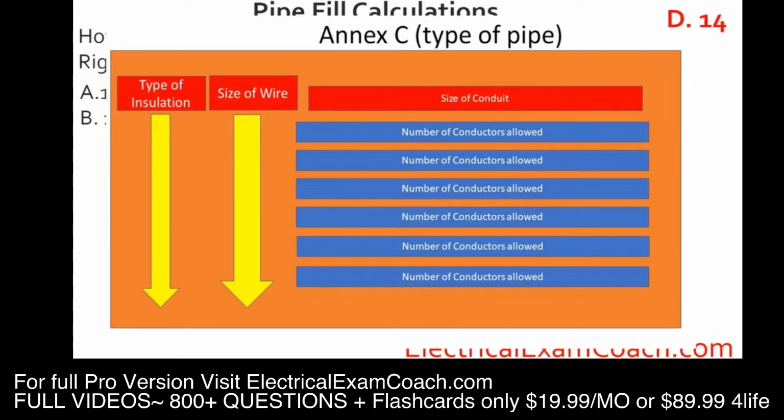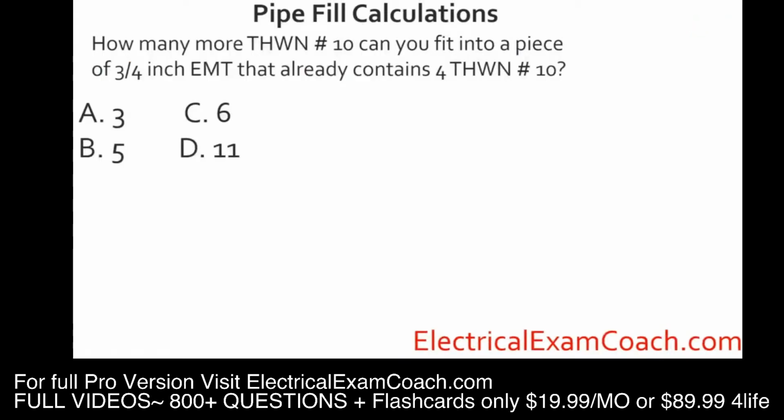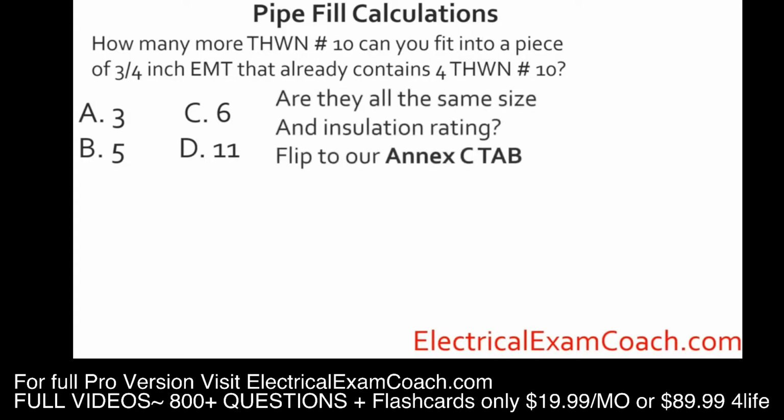Great job. How many more THWN number 10 can you fit into a piece of 3/4 inch EMT that already contains 4 THWN number 10s? The first thing we're going to ask ourselves, are they all of the same type and insulation? They sure are. So let's head to Annex C.